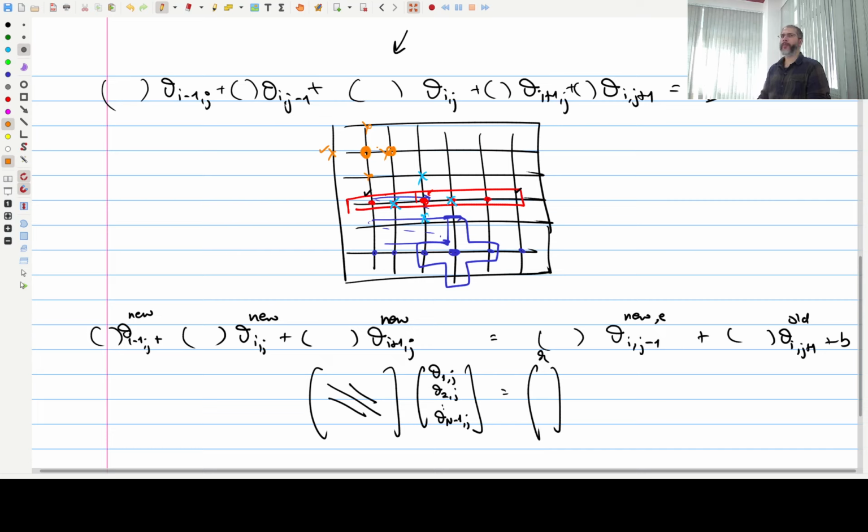So it could happen that the number of flops required for solving the TDMA could be the same or even more than the number of flops required if you have to explicitly visit each and every point. It could be the case, but generally, because of this idea of things being transmitted much faster, you tend to have faster convergence in terms of computational times. Iterations definitely are lower, but the overall time the computer takes will also be much lower in this case.